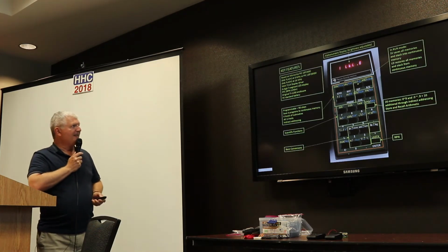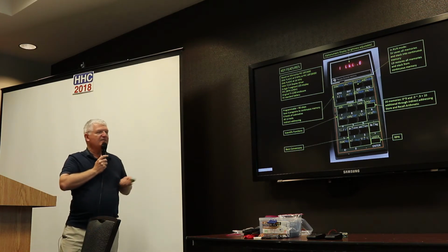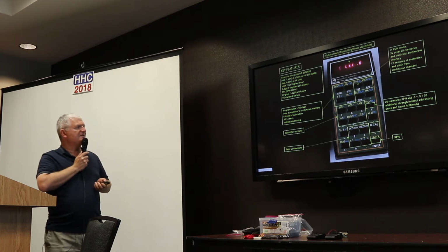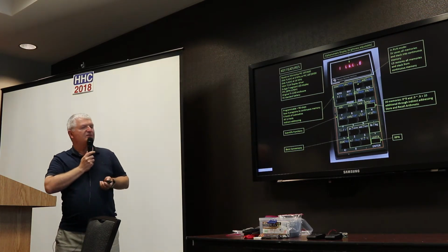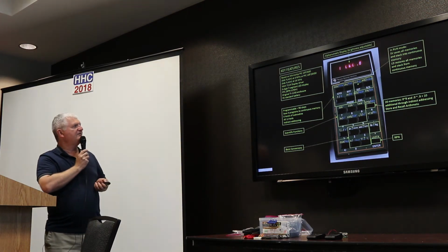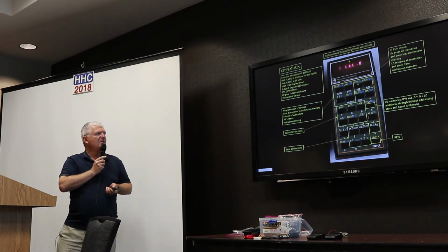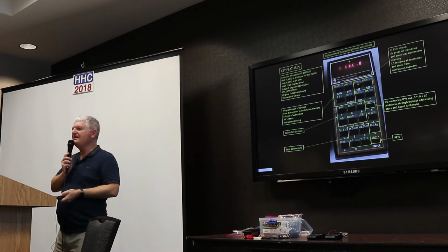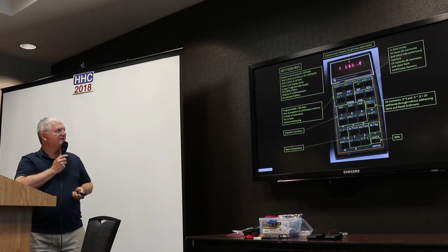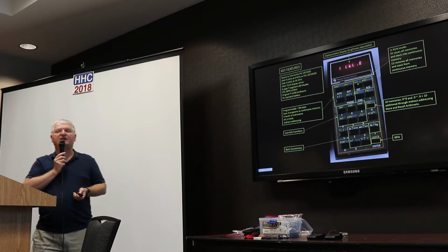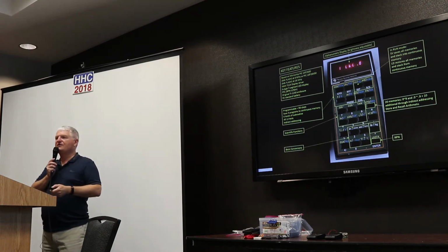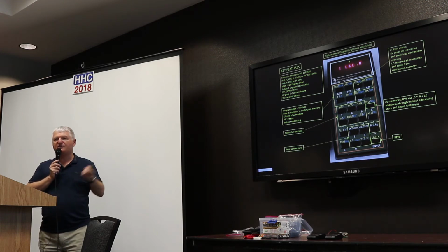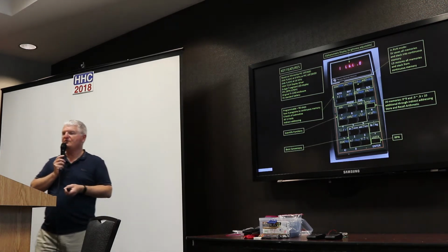wrap up. Key features: it's based on a Microchip PIC 18F, so there are different versions. 2680, it's 64K flash and 8 megahertz. Or recently I've used an 18F26K80, which is also 64K flash and 16 megahertz. Plus you can actually multiply the clock speed by 4, so you can run it at 64 megahertz, so it's pretty fast.